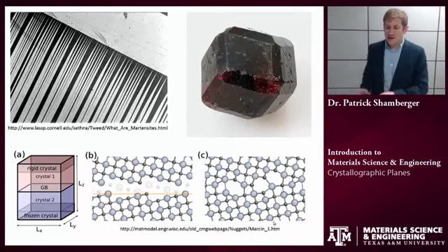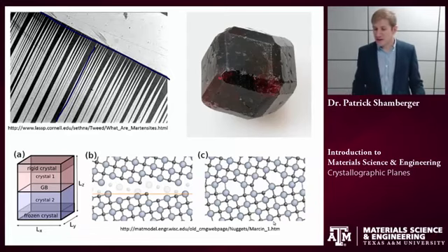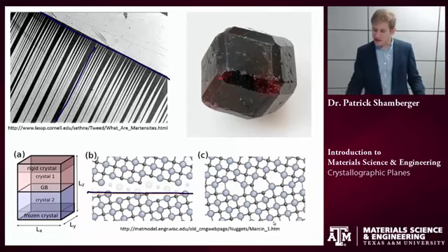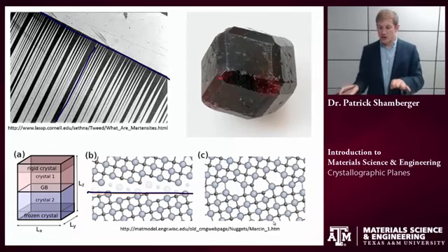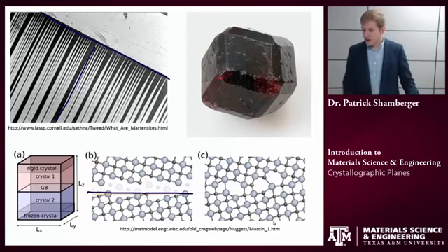If I'm looking at martensites, so this is twinning in a martensitic structure, and the twinning is observed along very specific crystallographic planes in a structure. Another example would be if I'm looking at the grain boundary between two neighboring crystals. So that is the interface separating two individual crystals, each with their own unique orientation.